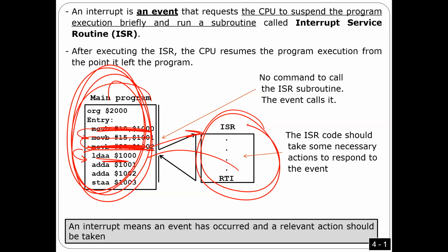Go run a subroutine, execute a subroutine related to this interrupt, and then I'm going to come back to continue again. So the way a microprocessor works, guys, is the following. This is the way it works. After executing every instruction, either I move to the next instruction or I serve an interrupt. It's called serve an interrupt.